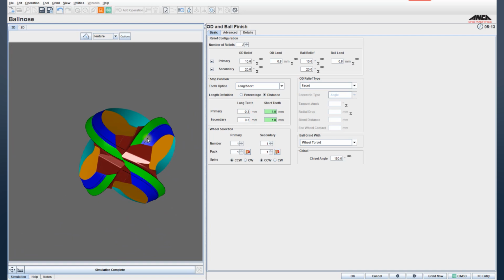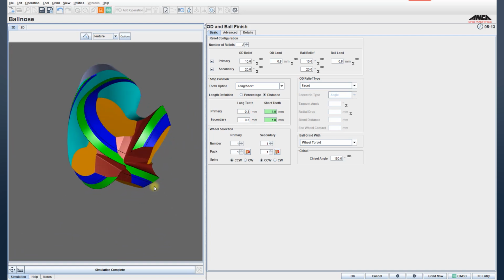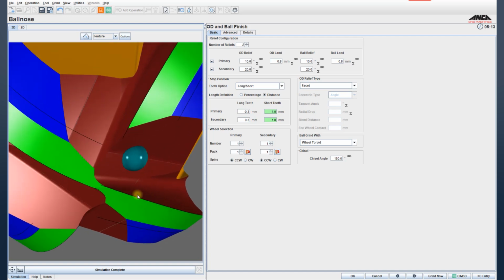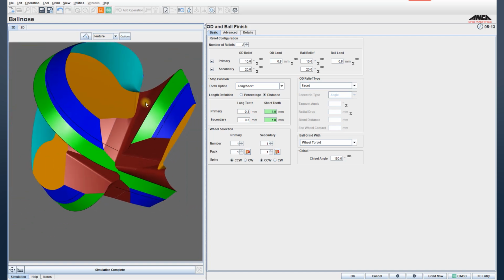So here's another tooltip, another feature which was introduced in RM35. This is quite beneficial, especially if you have multiple flutes with a different end face configuration, such as, for example, let's say a 6 fluted end mill. You could see that 2 might be coming to center or 3 might be coming to center. This stop distance would be much more beneficial in that application.